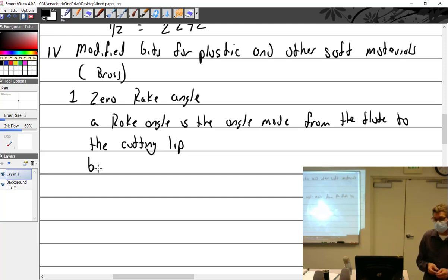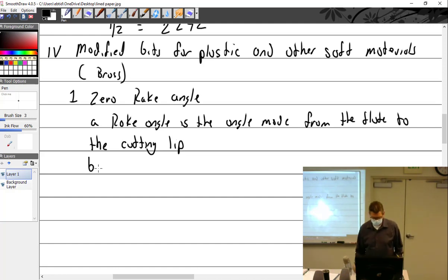And you can do this with any drill bit. I've never bought a plexiglass bit. I just modify them and put a piece of tape on it. It's for plexiglass. And if you forget and try and drill aluminum with it, you'll know in a minute. Yes, I'll pass it around. You'll see the 0 rake angleness of that. So in a pinch, you just make it. You put it on the grinder and grind that off. So there's nothing sharp.